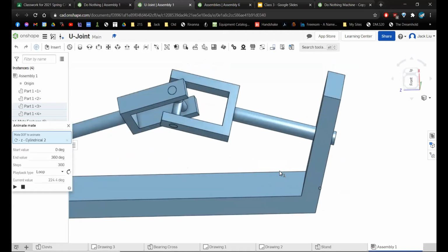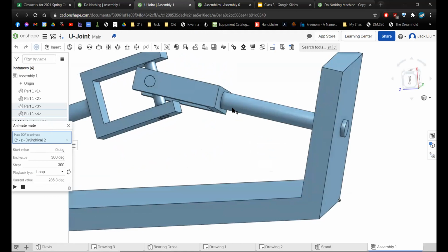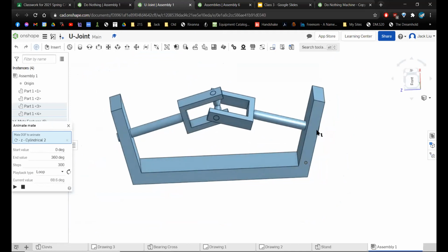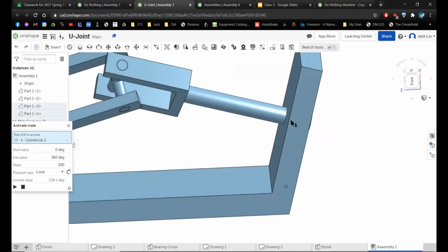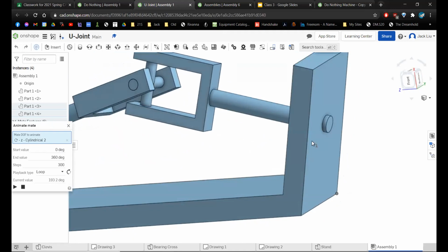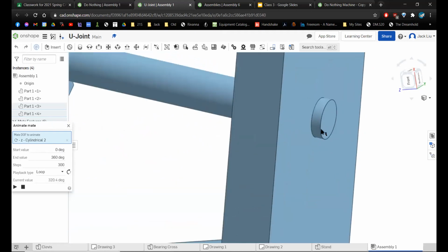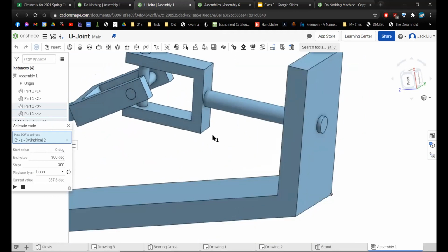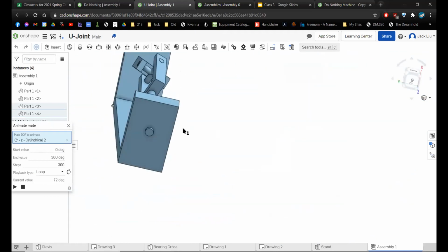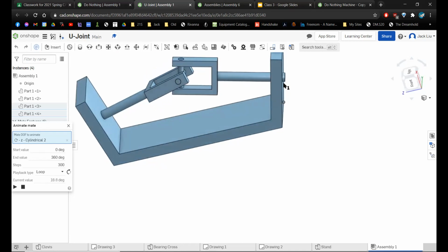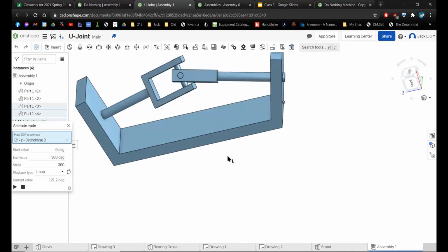And notice that the shaft of the clevis kind of sticks out a little bit. That's because of how the geometry works out, it has to stick out just this tiny bit. When you do a revolute mate, it tries to make it so that it's not sticking out. If you make one side not stick out and then make the other side not stick out, it's just impossible to solve. It's just impossible to do geometrically. And so you probably have some red mates. That's the issue there. So for these, we're not going to do revolute, but we're going to do cylindrical.